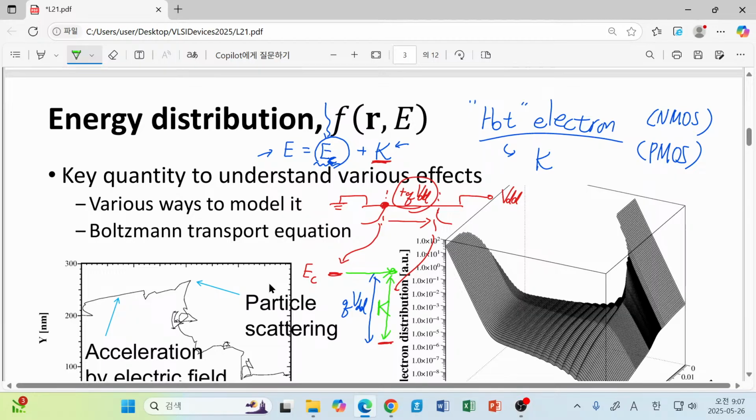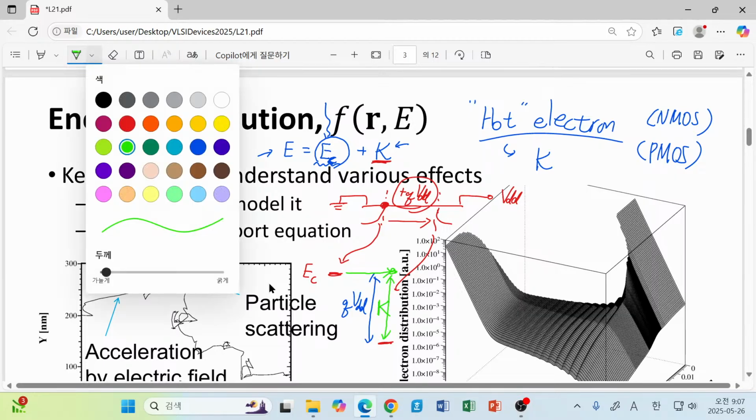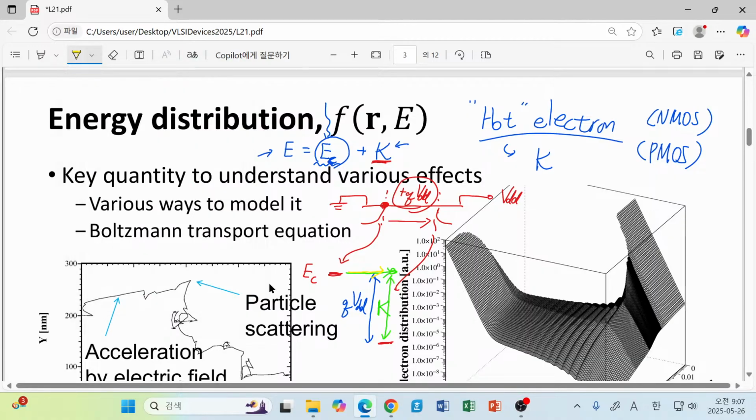Of course, I'm not saying that every electron keeps its original energy. This is really a rare case. In many cases, during its movement, there happens a certain event called scattering. So it loses its energy, and loses its energy again, and even when its journey is over, the probable energetic point is just around the conduction band minimum.